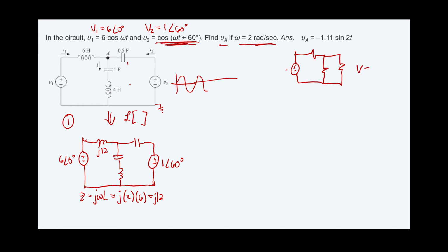So this follows Ohm's law, no? You remember V equals IR. Here we have V equals IZ. Although they're not confusing, they don't conflict with each other, but Z is R plus jX. And for the general term, Z is equal to R plus j(XL minus XC), the inductive reactance minus the capacitive reactance. We also discussed this one in one of the lectures, but so far we don't need to go that deep.